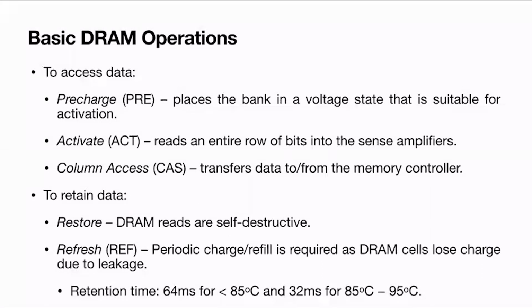And if you see some of these latest DRAM DIMMs, which have a capacity up to 32 GB or something, in such high density DRAM devices, your refresh operations are actually occupying almost 25 to 35% of the total time. That means during the time when the refresh is happening, if the CPU side sends any request to that particular bank under refresh, that request cannot be serviced because refresh has the higher priority. Once you are doing a refresh, any request from the processor side will be stalled. So once it is stalled, the processor side will see a significant performance degradation.